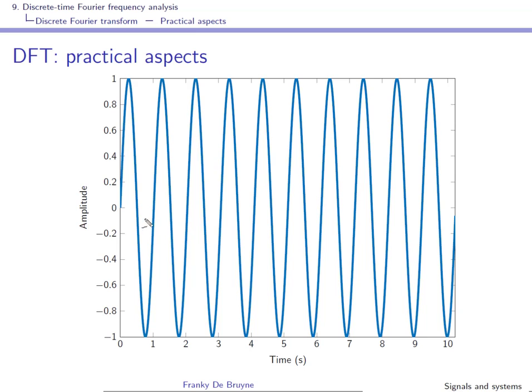You can see that if you repeat this signal, you will have continuity because the next sample will be 0 and we will keep the periodicity. If you let the signal start at 0 and finish at 0, then you'll have a 0 and a 0 again, and you'll have a little bit of spectral leakage.